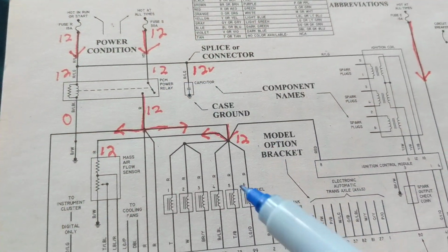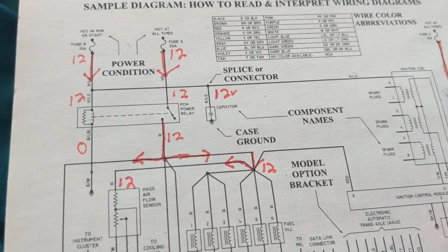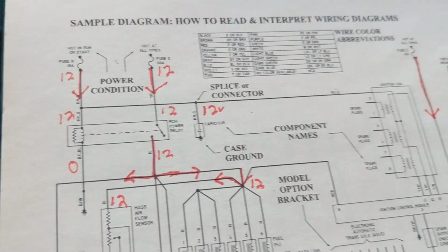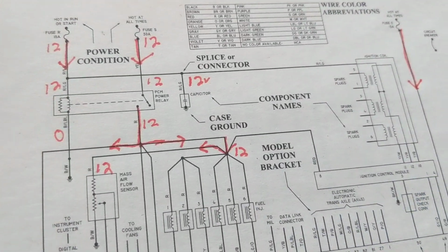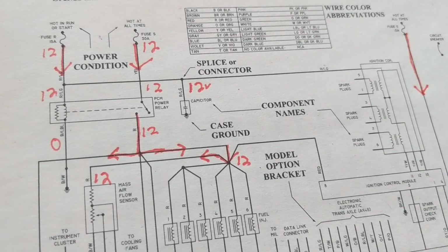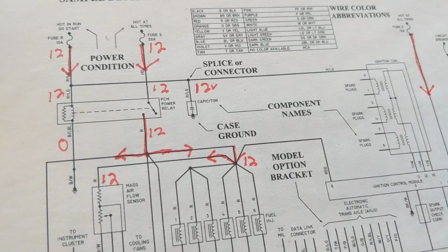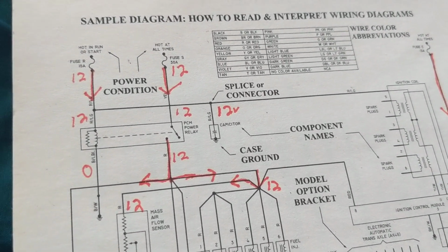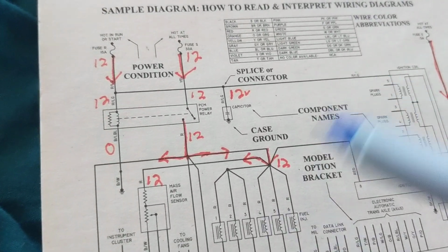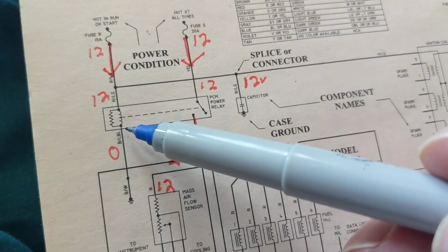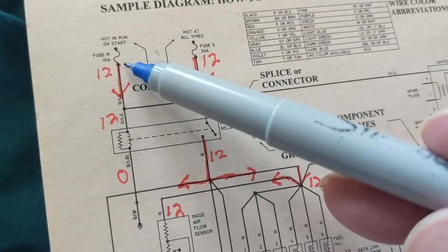So, here's a relay. And this is why I picked it. This is for BMW, but so is the case, the scenario for most vehicles. Relays are abundant, and they are all over. That's the first thing that you think of when you have an electrical problem, is the relay activated. And how do I go about troubleshooting it? What's the first part we always talk about that has to be activated? This side, the coil side. So it always comes from a fuse.